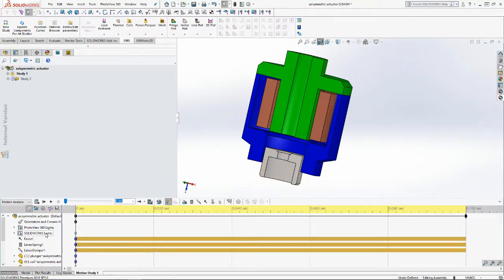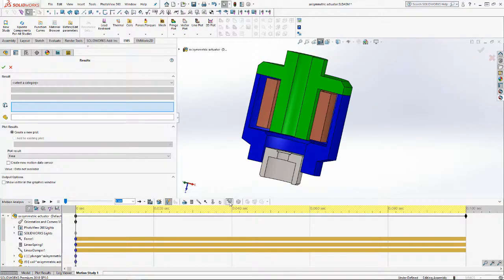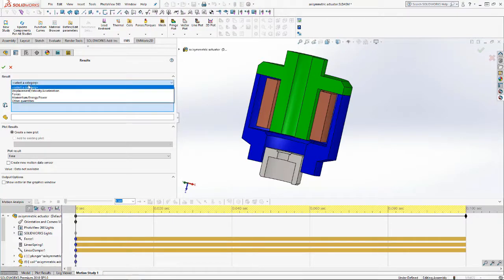So combining all these settings, EMS will compute the force, then SolidWorks Motion uses that force, in addition to what is there, like spring, damper, maybe gravity option, maybe linear initial velocity or whatever, and combines them to compute the mechanical results, displacement and maybe speed, acceleration, and so on. So you can plot also the mechanical results using these plot options. You can choose whatever you want: displacement, velocity, force, and other quantities.